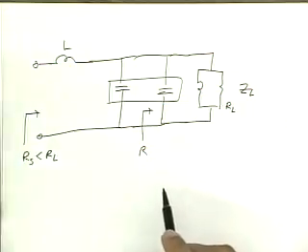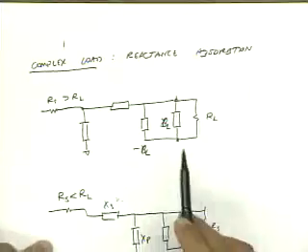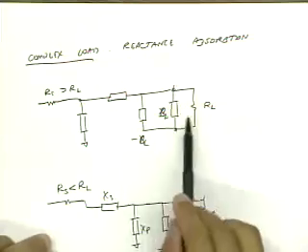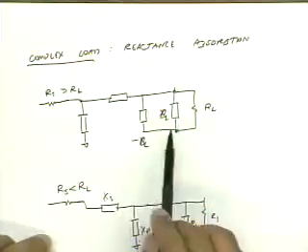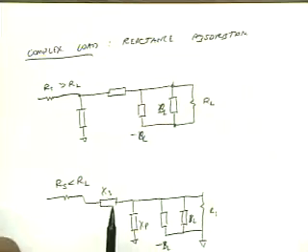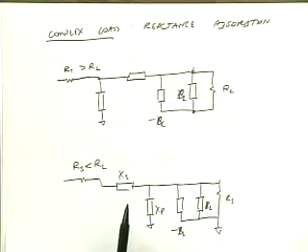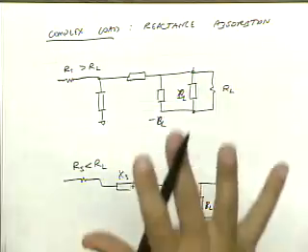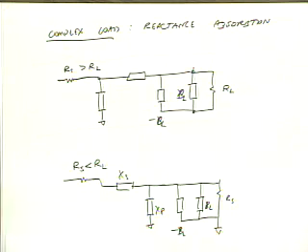So that's why we call it reactance absorption, because a lot of times we can absorb the complex part of our load and source into the matching network itself. So even though for the matching networks we've discussed up to now, all the design equations were for real loads and real sources, you can see that it very simply generalizes to complex source and complex load. Okay, any questions about that?